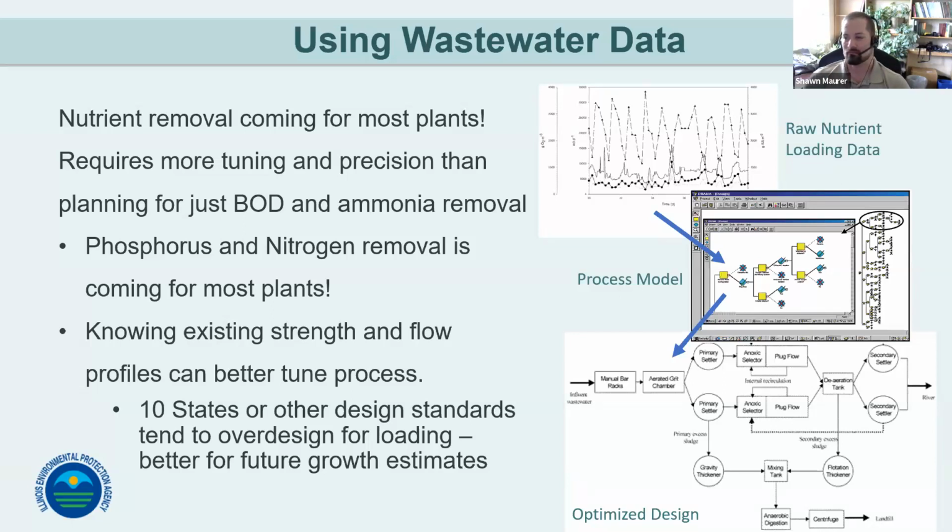One thing to note, with a lot of designs that follow 10-state standards or other design standards, they're planning for that future growth, and so they'll upsize your facility. A lot of times they have some conservative design standards in them that for most plants ends up oversizing equipment. While that's good for designing for future loads, you also need to take into account your current loading and make sure that your equipment can either stage down or has variable speed controls or some kind of modularity built in to handle what you have now, so that you're not operating inefficiently now, while planning for operating efficiently in the future as loads change or increase.